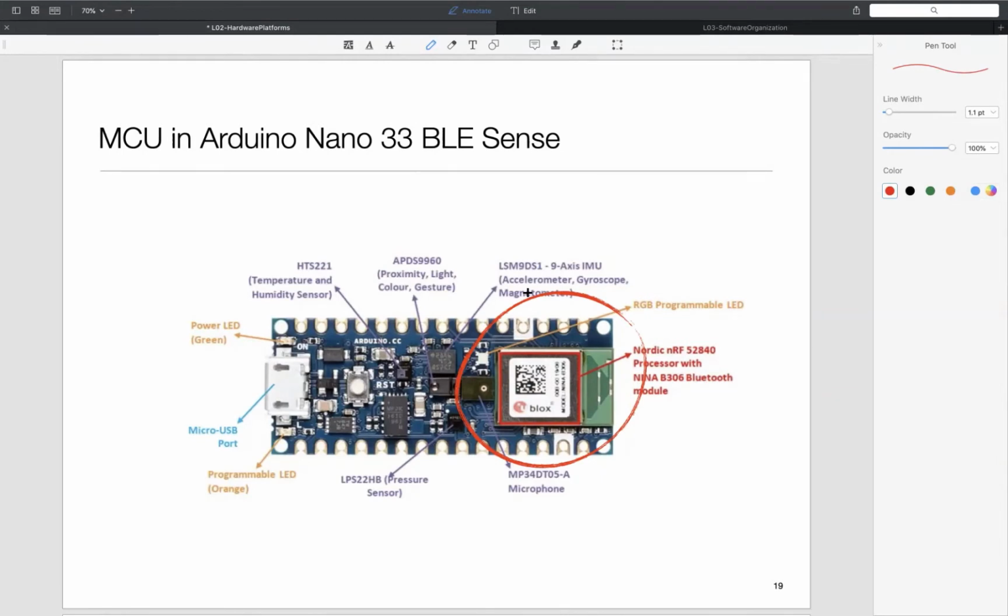So it gives you three degrees of magnetic field, right? So you can also get whether you are pointing up or down relative to Earth's magnetic field. So it's not simply telling you the angle with respect to the magnetic north, but it's also telling you up and down relative to the magnetic field around the Earth. So collectively, these 9 degrees of freedom information is giving you a lot of stuff around it.